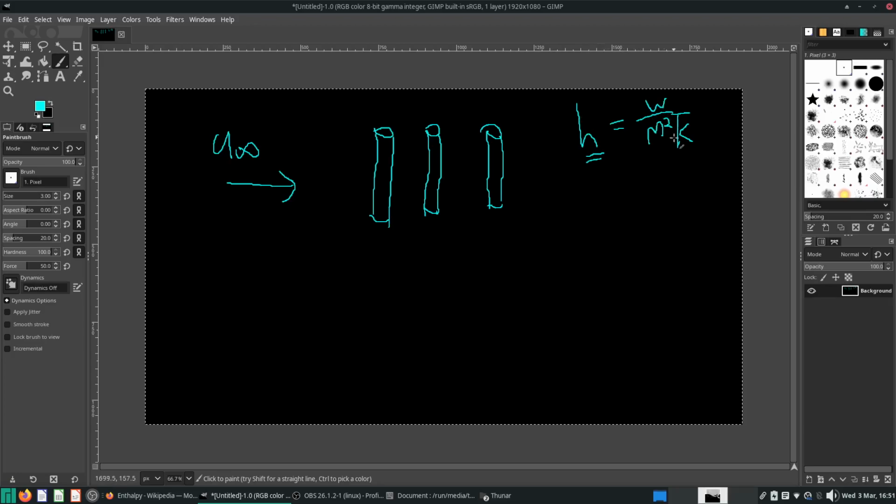So it's energy per unit area per unit time. This is what is usually calculated, and it's usually given by some Nusselt number, Nu. Nu equals some function of the Reynolds number and the Prandtl number.